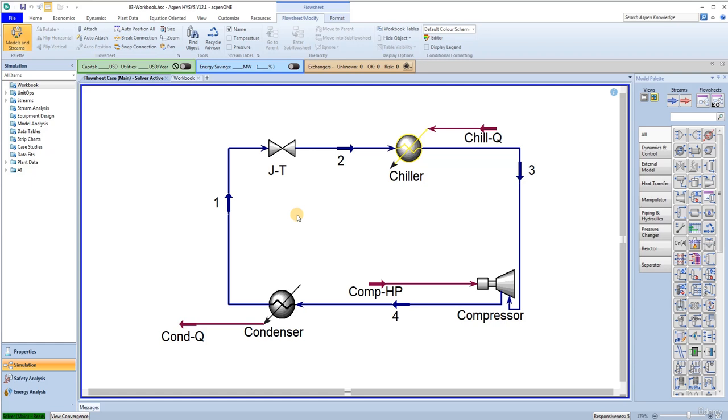You can perform many of the tasks and manipulations on the icon of the flowsheet by using object inspection, right-clicking the object you want to inspect. An appropriate menu is produced depending upon the icon selected, either stream, operation, column, text annotation, etc. To show the object inspection menu for the flowsheet background, right-click on any empty space on the flowsheet.